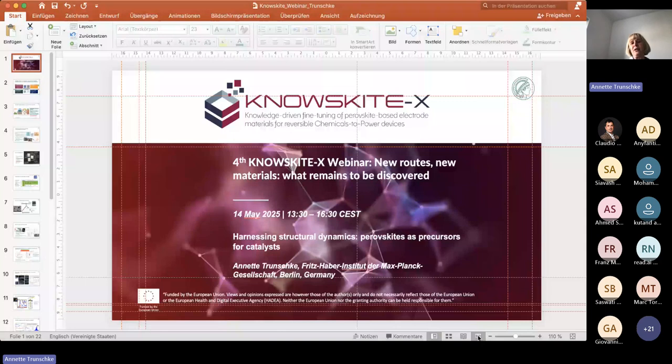self-combustion. And after that, we usually calcined all our synthesis products at the same temperature to have a similar starting point regarding the oxygen defects in these materials. And in some cases, we directly obtained a phase pure perovskite. But in some cases, we had some incomplete conversion of the perovskite phase or presence of side phases, which required a washing step. And this washed material was again then calcined at 800 degrees in air. And this we normally don't need to do by applying flame spray synthesis.